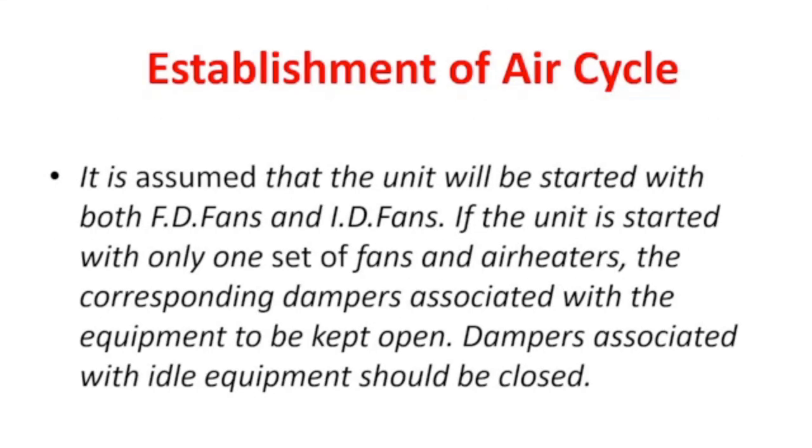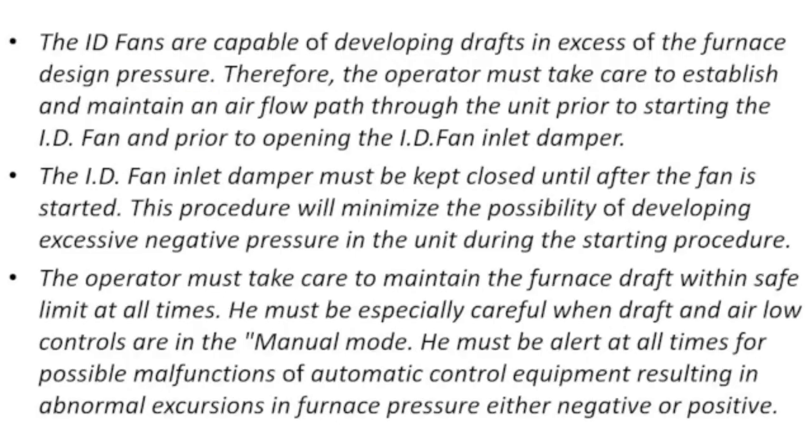Now, establishment of air cycle. It is assumed that the unit will be started with both FD fans and ID fans. If the unit is started with only one set of fans and air heaters, the corresponding dampers associated with the equipment are to be kept open. Dampers associated with idle equipment should be closed.